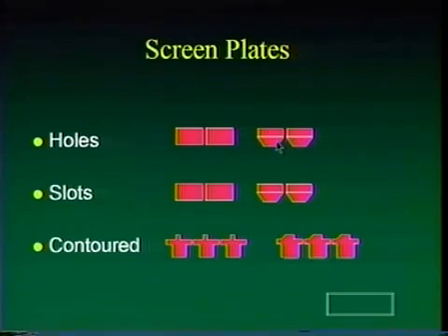But as machining capabilities in the United States or anywhere have improved, it's easier and more economically feasible to make these tapered openings that improve our screening. So you will often see tapers on the accept side. I should mention, this is the feed side, this is the accept. Feed, accept. And so you'll see these tapers, and they help throughput.